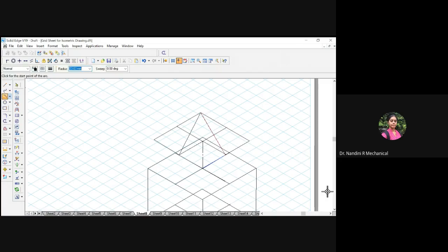From arc to the radius, you just show, and similarly go for corner to the end point. I am showing you the rough construction. Use the compass and scale properly to join. After that you will use one end of the compass here, connect the other at the distance of the radius, and you will cut an arc.